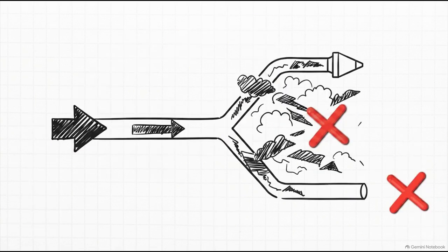Well, you've just spotted a classic field problem: shared air demand. The system simply doesn't have enough compressor capacity to power both the main nozzle and the blowpipe at the same exact time. The required action here is black and white. The crew cannot shoot and use the blowpipe simultaneously until they bring in a larger compressor. It's a fantastic reminder that you have to evaluate the equipment as one complete interconnected system.